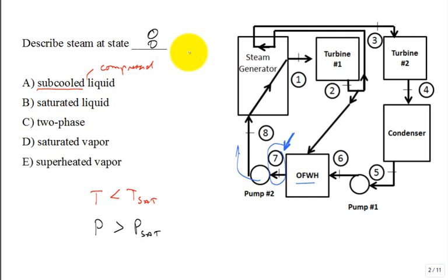If you want to confirm that it's subcooled, knowing the pressure, get the saturation temperature at that pressure and compare the actual temperature with the saturation temperature. If it's colder, we would say, oh, that's subcooled liquid.